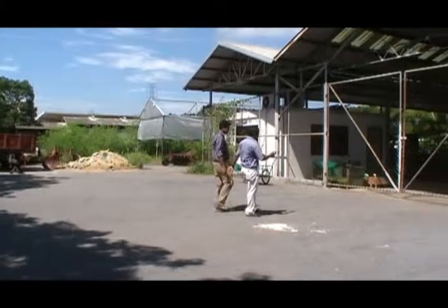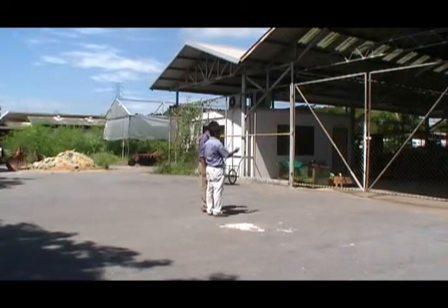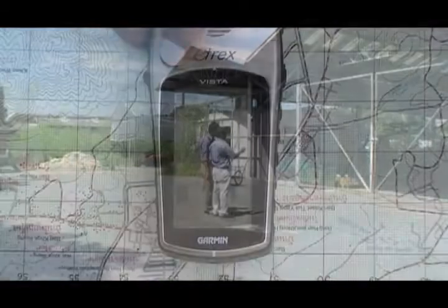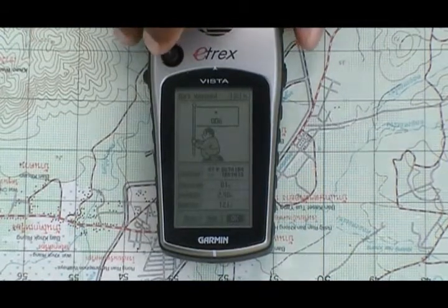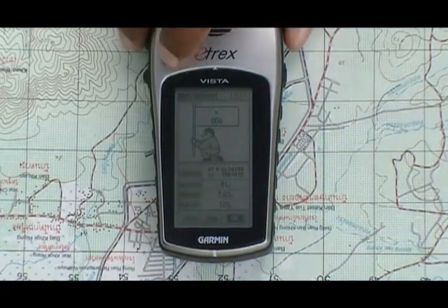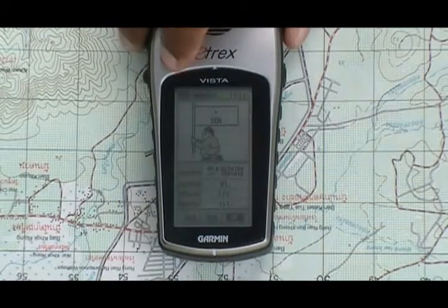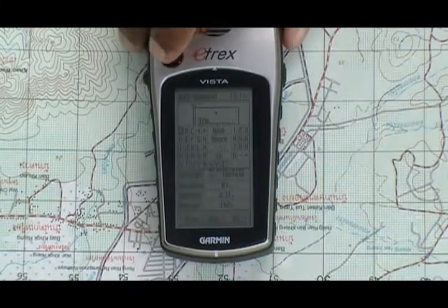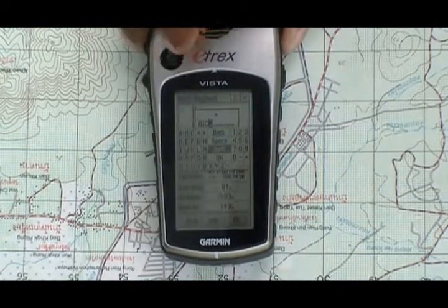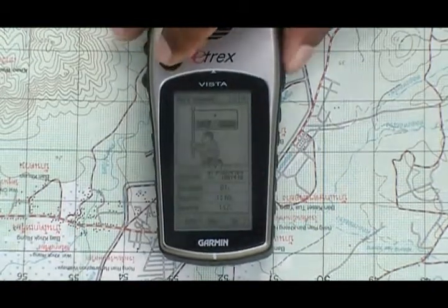To save the current position as a named or numbered waypoint, you must access the function for your unit that does this. On many of the Garmin units, the Mark button is specifically for this purpose. The naming process is usually simple, using the up and down arrows of your keypad to choose various letters and the left and right arrows being used to move to the different characters.